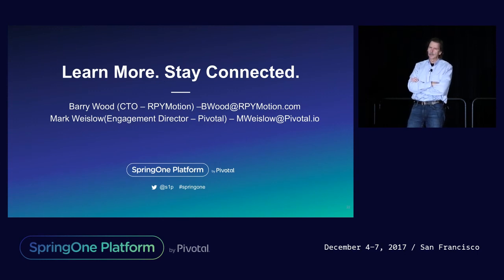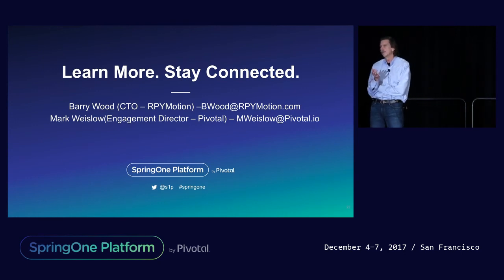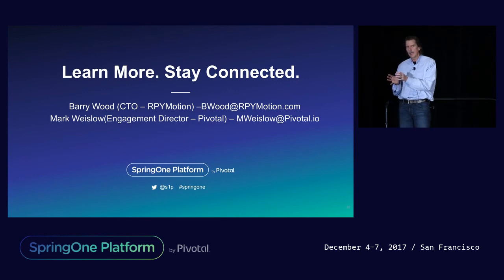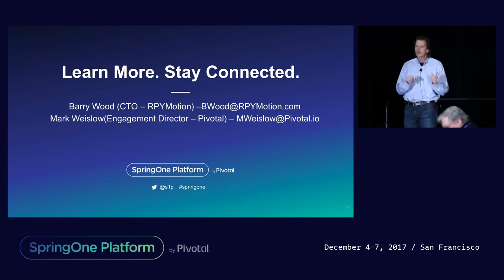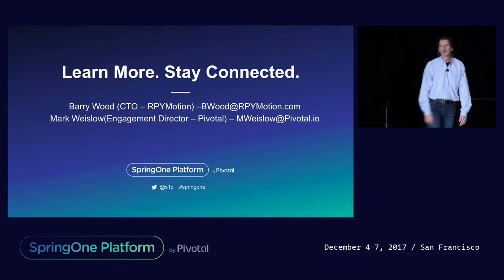The issue is that everyone who has tried a solution was trying to do the entire solution in a PLC. And they had lost the ability I mentioned about having configuration files. With a traveling head die cutting press, you have a control program that defines the cuts, and you can have hundreds or thousands of these programs. So what we did, we implemented this solution where we used the IoT Bridge and stored the programs, and then when they got ready to run that particular die, we loaded that program in, but we still did all the machine control with the PLC. Yes, it's actually in production.